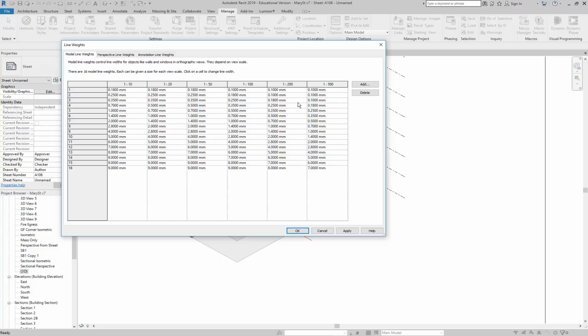Right. So in AutoCAD, this has been a problem for years. For 40 years, people have been struggling with this because you would have, let's say, a wall layer for cut and a wall layer for not cut, projection or elevation or whatever. So you'll say, okay, walls when they're cut in plan, what's the line weight? Let's say 0.35 is pretty standard. There's no rule because it varies according to your own style, but it should be heavy when it's cut.